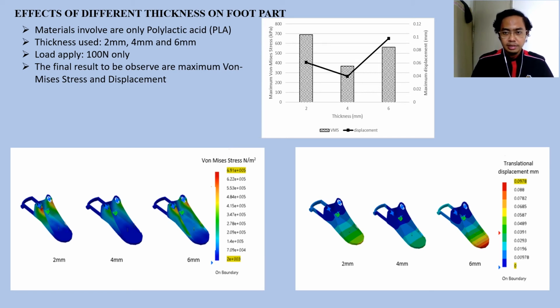the bending stress is high at 2 mm, decreases a little at 4 mm, but rises back at 6 mm. Now, this is quite logical because, as you can see in the static analysis here of the bending stress, in the picture on the right below part of the slideshow, the stress occurs near where the clamp force is.